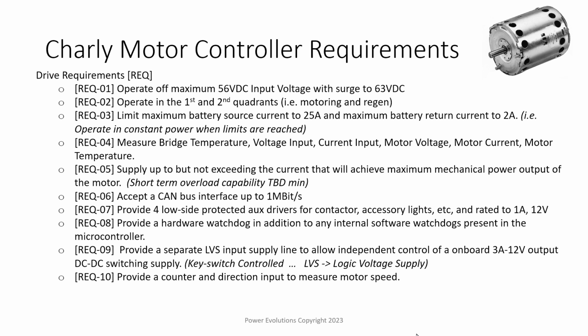Another thing we need is to have a separate low voltage supply input line. So that's the battery voltage coming into a DC-DC switcher, which is generating the local logic voltage supplies.